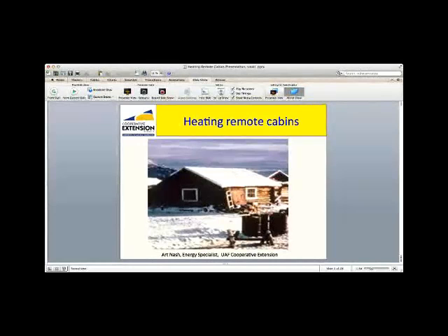They would go ahead and lay it flat, cut a hole about 8 inches in the top of it, and stab through a stovepipe. Of course, they go through the roof the same, and then they put it on a small stand to keep it about a foot off the ground, or maybe 2 feet off the ground. And then on the end, where the drum lid would normally go, they cut a square and put a little hinged gate in there, and voila, out of a 55-gallon drum, you would have a drum stove.